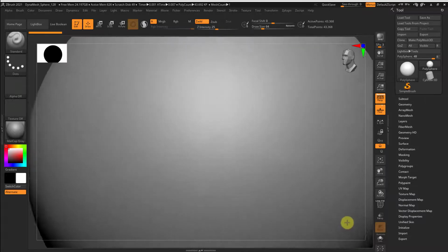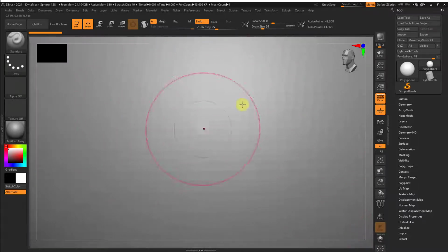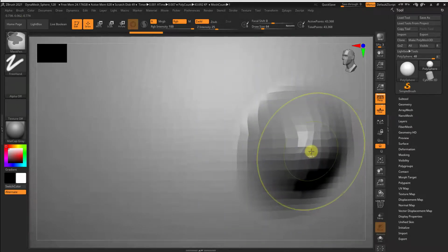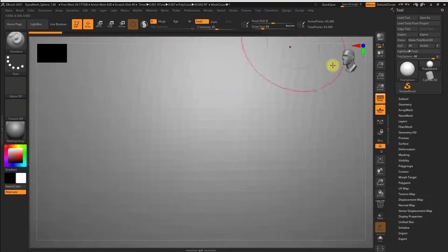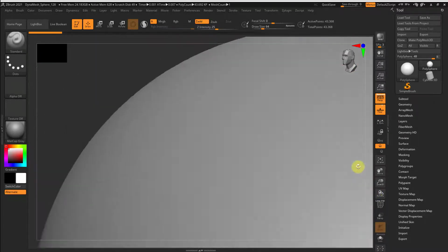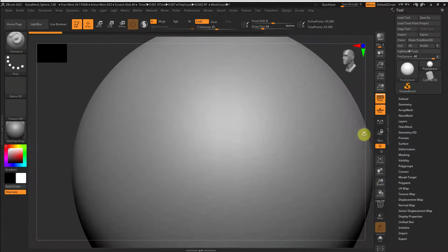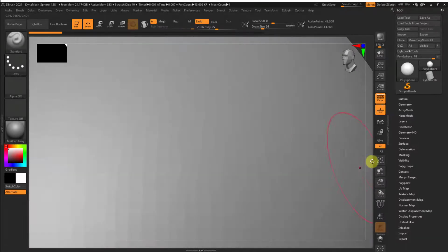Let's say I'm zoomed in very close to my sculpt and I need to work on some finer details, and I can't zoom or pan because I'm just clicking on the mesh, right? And I'm sculpting. So if I need to pan or rotate or zoom, I can hover outside of this little white square outside of the frame, and that will be the same as clicking outside of the mesh, okay? So if I'm zoomed in really close, again, I can just click out here and drag around.